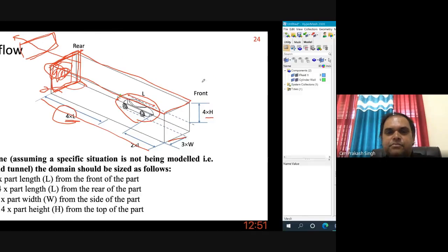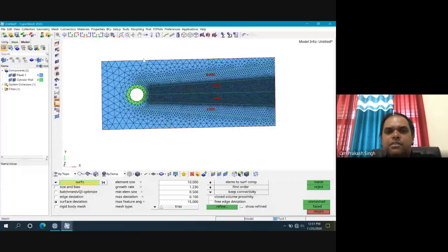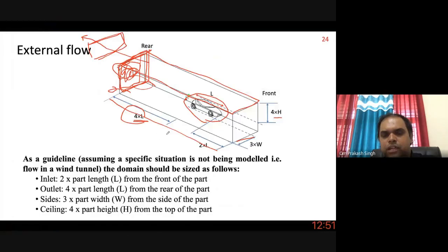So here in all these walls, top wall, since this is a 2D problem, so this top line and bottom line, ideally you should be giving a slip boundary condition. And this length ahead of, because just in front of the cylinder, the fluid will strike and tend to bend a little bit. So you should give a length of how much it's given, 2L. So here 2L.